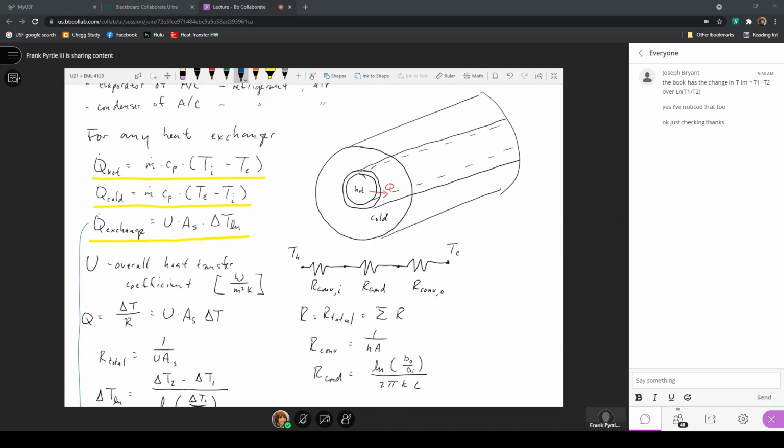We're also considering concepts from chapter 8, which allow us to calculate heat transfer coefficients based on flow conditions, and consideration that heat transfer coefficients do change along the length of a flow path. So those are put together in the expressions of heat exchange between hot and cold fluids.